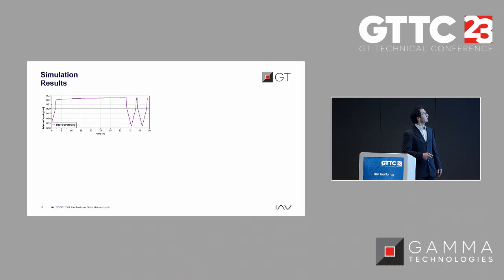Now I go to the simulation results. Here you see a time plot of similar scenarios as before. It is plotted the relative capacity in ampere hour over time. And we can directly get from the simulation software the delta from the start of the CV phase until the end of the CV phase, so 36 hours. And we get a difference of about 2%.